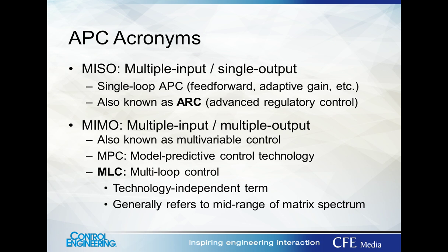I have divided this into two parts, conventional MPC and multi-loop control, or MLC. The term MLC is adopted here to meet two needs. One is to provide a technology-independent term for MIMO control, or for multivariable control, and the other is to refer to the middle region of the APC matrix spectrum.